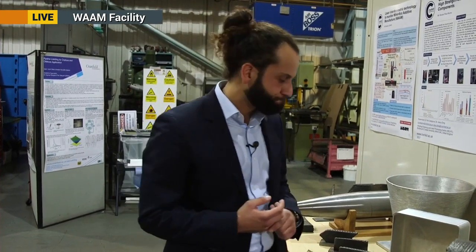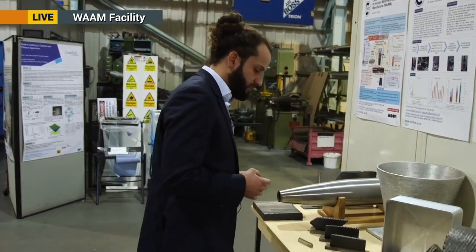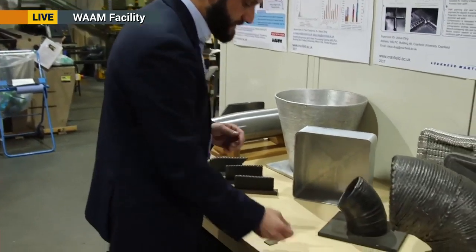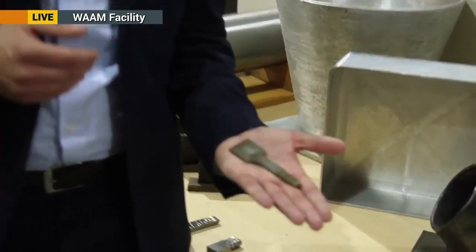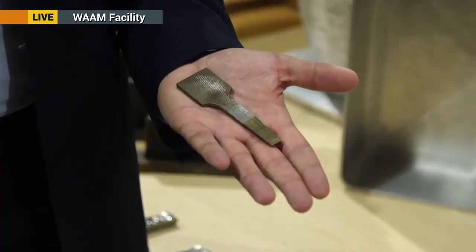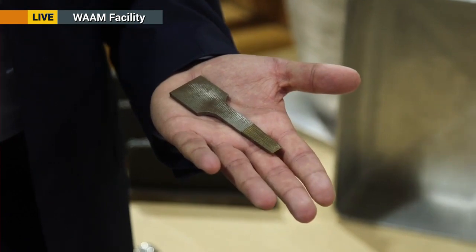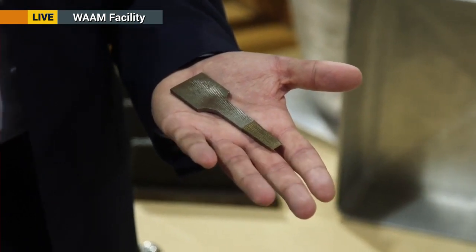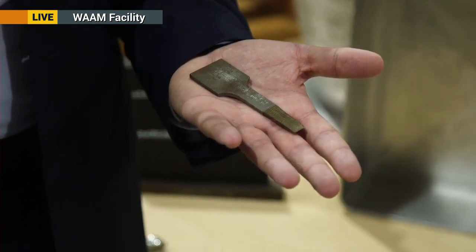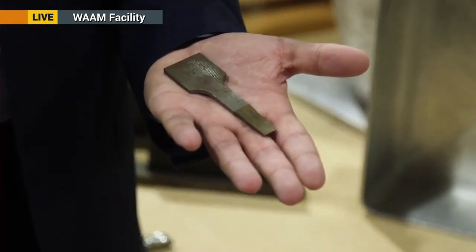And of course, between one and the other, typically we would have to resort to a stress relieving heat treatment to reduce the residual stress and the internal tension, but these are established processes that have been around for decades. As I was mentioning multi-materials, I'm just going to give you a quick example of a specimen made in a graded way from steel to a copper-based alloy. Provided that the two materials are metallurgically compatible and they expand and contract in a comparable way, actually it's quite straightforward for us to go from one to the other.